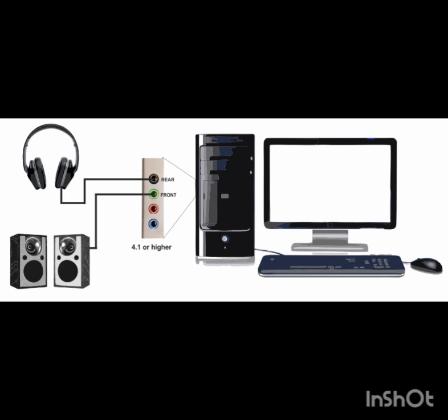The operating system uses a device driver to communicate with the sound card. Once the sound card receives the data, it converts the digital audio data to an analog signal using DACs. The analog signal is then sent to the speaker or headphones to be heard. Some sound cards also have features like DSP, or digital signal processing chips, which allow for additional effects like surround sound or equalization. Now, there have been some advancements in sound technology.